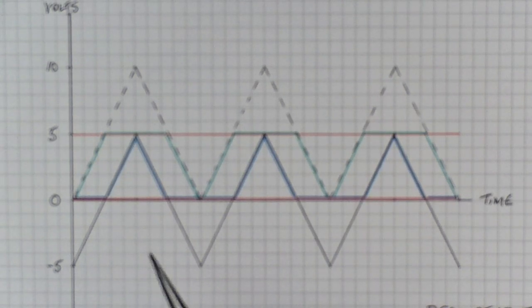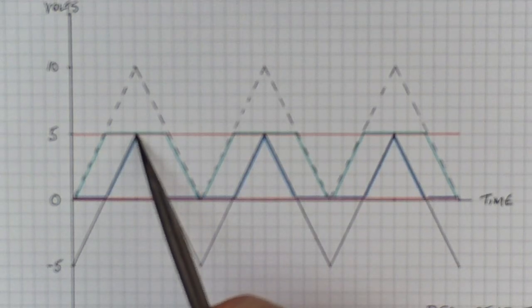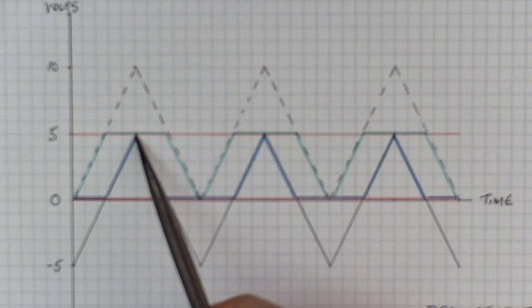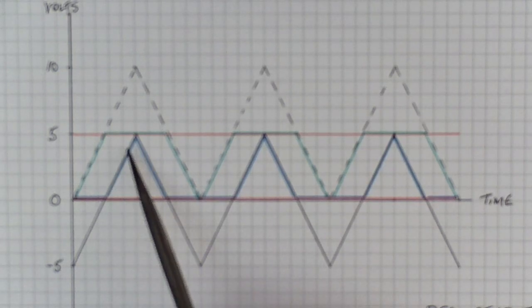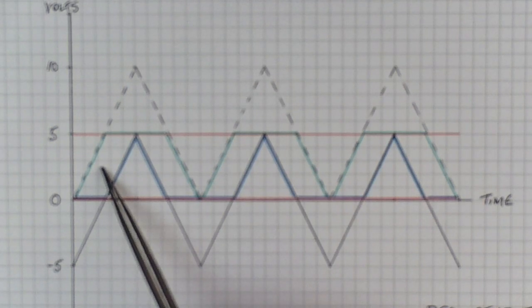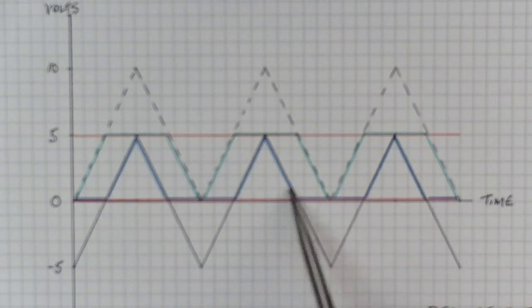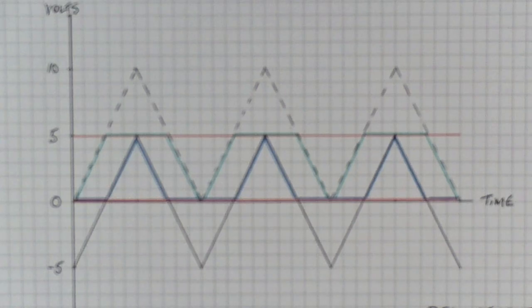So what we need to do is design a circuit that takes this minus 5 to plus 5, and first of all, attenuates that so it's just between 0 and 5. We also then need to offset the attenuated triangle so that it is centered at 2.5 volts, so that we get the full triangle waveform between the values of 0 and 5, so Rorschach can use that voltage across its full range without any dead spots.